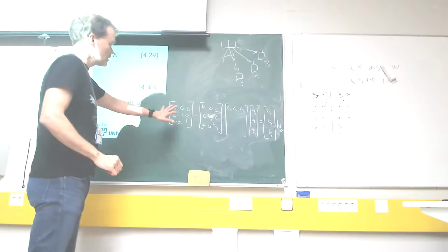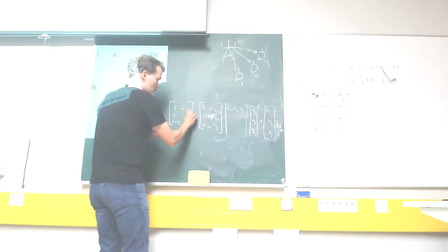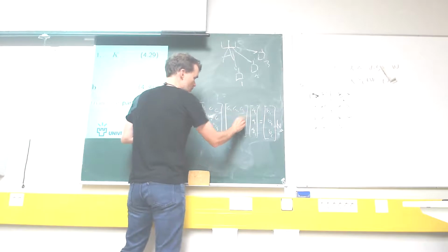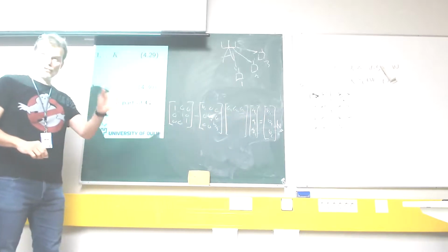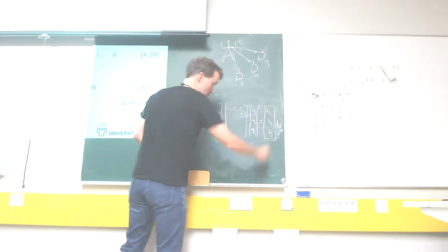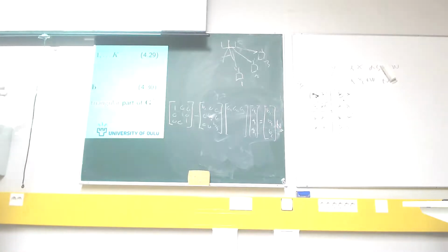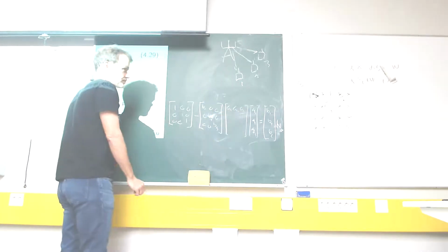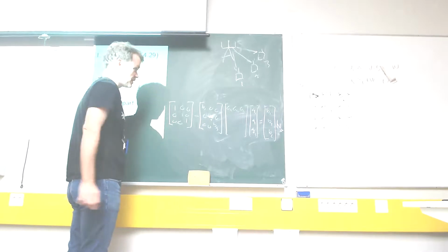Right? So this first row here corresponds to the first user. Times the powers we get b_1 times N0, which is equivalent to the SINR expression. Just multiplying the left-hand side with the denominator and adding the missing term, you get this expression. Just rearranging the SINR form.